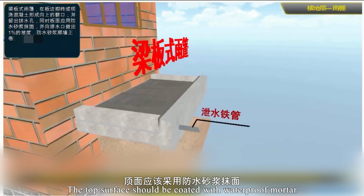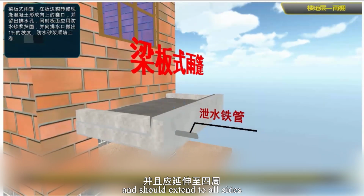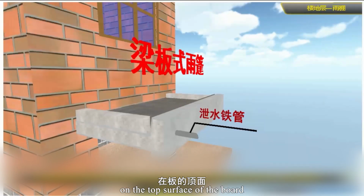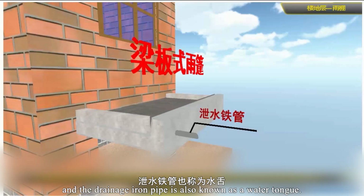The top surface should be coated with waterproof mortar and should extend to all sides and turn up to form a flashing. Organized drainage is adopted on the top surface of the slab, with a 1% drainage slope toward the drainage outlet, and the drainage iron pipe is also known as a water tongue.